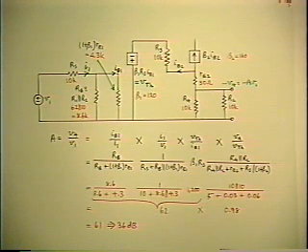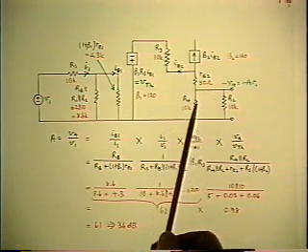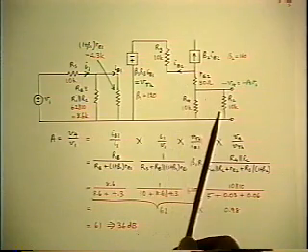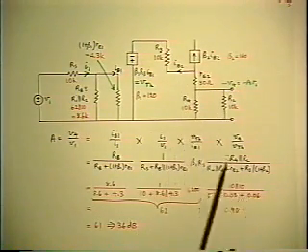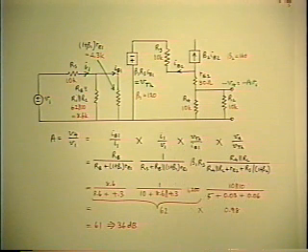Anyway, you may remember that you can reflect impedances between primary and secondary of a transformer according to the square of the turns ratio, which is really the product of the current and the voltage ratios, but a transistor reflects it only according to the current ratio. So it's not the square of beta, it's only beta, or 1 plus beta.